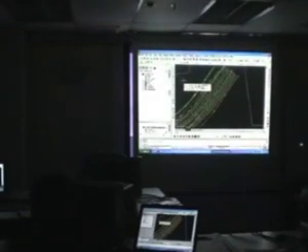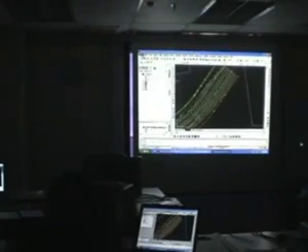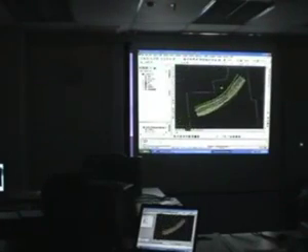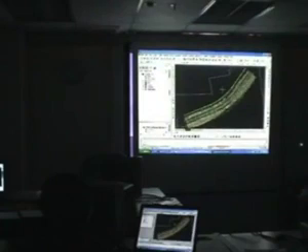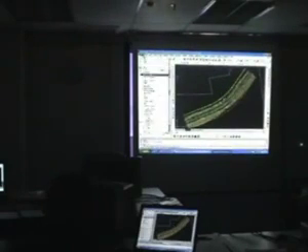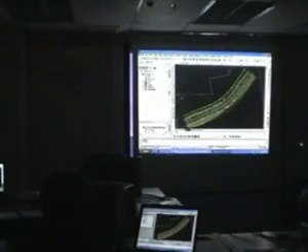Of course, Civil 3D does not come with that wonderful package of Autodesk Viz, but it comes with what is useful in Viz for civil engineers. So we call it Viz render. We've got a corridor here, and we want to see what this looks like, maybe with the asphalt on top and the grass at the side. You want to see what it really looks like. That's what Viz render is for. So you just click link to Viz render.